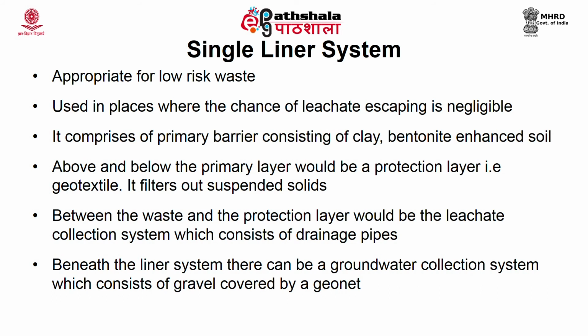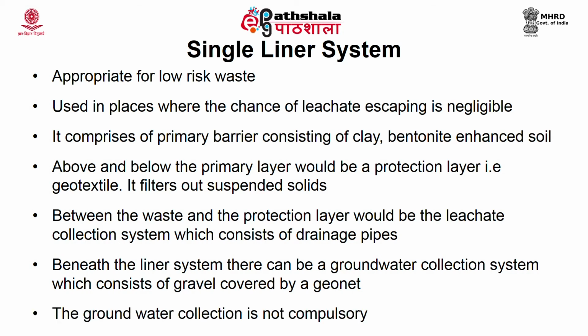Now, beneath the liner system, there can be a groundwater collection system which is made up of gravel covered by a geonet. Now, this is an optional layer. It is not necessary that every liner system should have a groundwater collection system. So, it is not compulsory, it is optional. If you want, you can have a groundwater collection system.